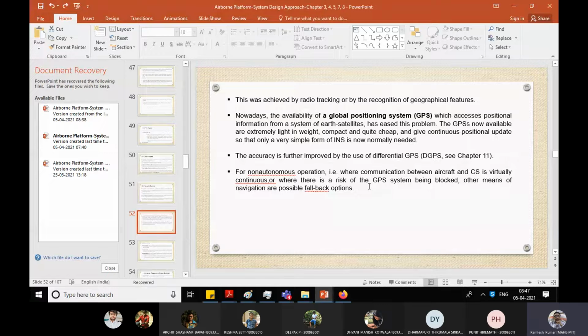Okay. So you get, from the internet also, that for this particular area these are the satellites that should be available. The receiver will pick up only those satellites without getting any external information. What is the meaning of this? First you locate your satellites' positions, then you make them active, and then you use that basic idea to calculate positions. Every time you have the positions of the satellites known, then with the distance covered between the satellites and your receiver, you can do the position calculation on the receiver side.